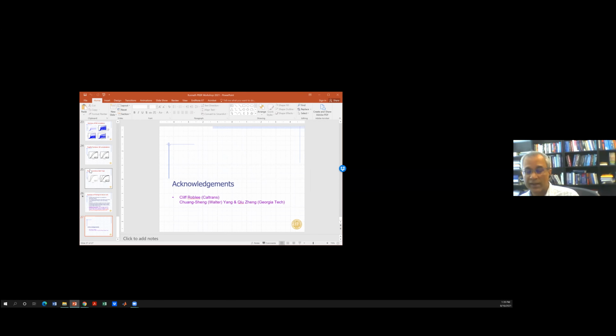In our case, the vertical load we're applying is the axial load in the test. And bridge columns typically don't have very much axial load. It's about 10 to 15% maximum. And so to actually get a gravity collapse is kind of difficult. So I would say that damage states 6 and 7 kind of merge to some extent. When multiple bars rupture, we basically call that collapse as well. I don't know if that adequately answers the question. Yes, thank you, Sashi. You answered my question.